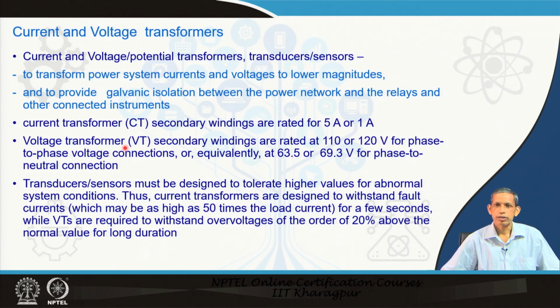So, the practice of these CTs and VTs is pretty old, and they were being used when electromechanical relays were there in the high voltage system also. So, from a retrofitting perspective, the corresponding CTs and VTs are still continuing. In that respect the numerical relay may use subsequent scaling down of the signals, incompatible with its own internal arrangement.